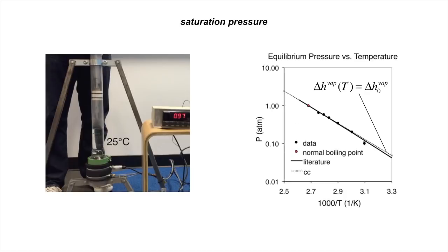Shown here is an Arrhenius plot of the saturation pressure of H2O as measured using our transparent piston cylinder assembly from episode A4. Plotted along with our data are data from the steam tables, shown as a dark black line. The dotted line is the dependence predicted by the Arrhenius dependence we just derived, based on the enthalpy of vaporization at 100 degrees C. As you can see, the result is fairly accurate, but fails to capture the slight curvature